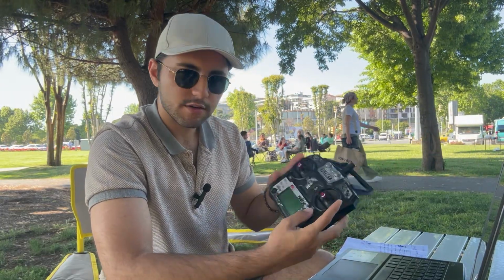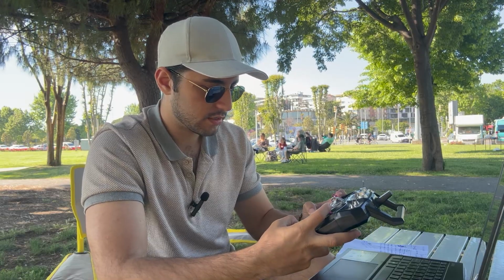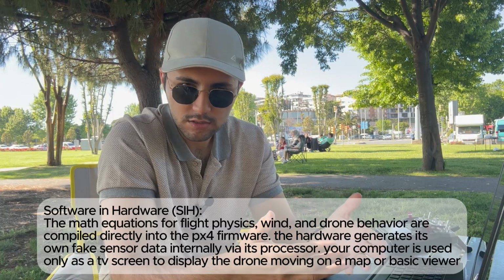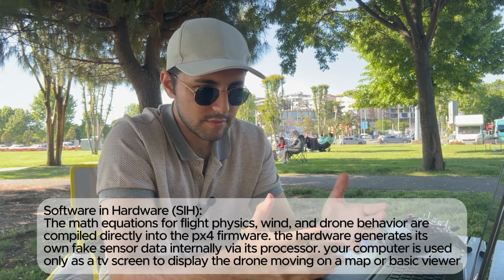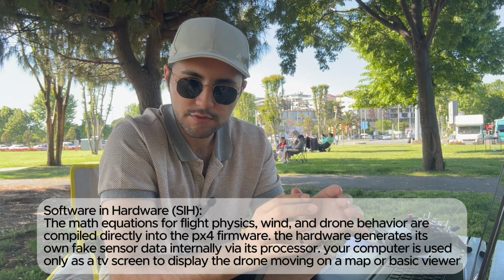Then I have my FlySky i6X model. I'm going to connect this. Now, what you need to know is that in PX4 1.16, they have categorized the simulation. One is SIH, which is software in hardware. Basically, this means you are simulating the model from the mathematical model of the drone, on the flight controller. The other one is hardware in the loop, which is HITL.